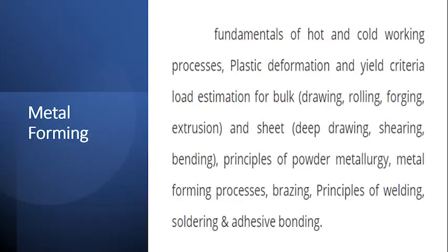In the last session we had two doubts. First was regarding centrifugal casting and second was the riser. In centrifugal casting, if the question mentions that it is horizontal, then you have to take the outer diameter. If it is mentioned vertical, then you have to take the mean diameter.